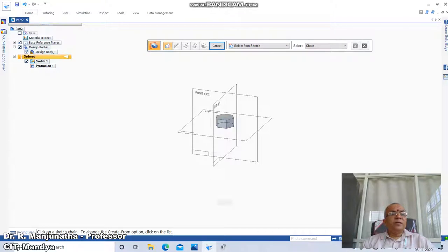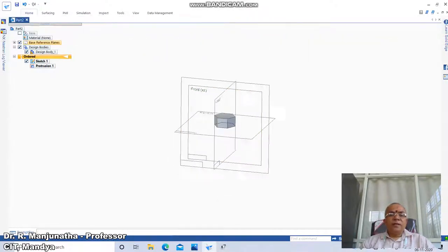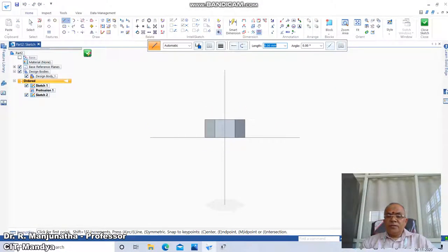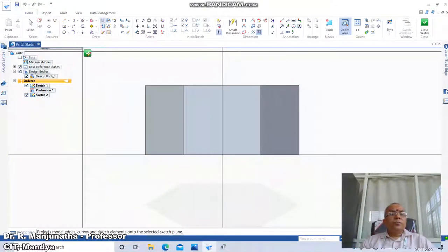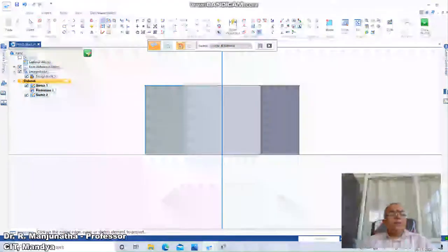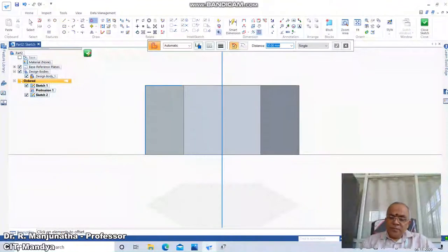To create the chamfer, click on home, click on sketch. So click on the front plane. Then you come to zoom area. You just select this, it's a zoom area. Then go to project to sketch. Click on OK. Click on this line and this line and this center line. Then go to 0.2D. So go to offset. 0.2D means 0.2 into 16, which is going to be 3.2.